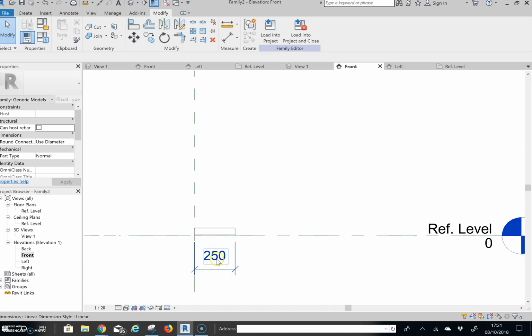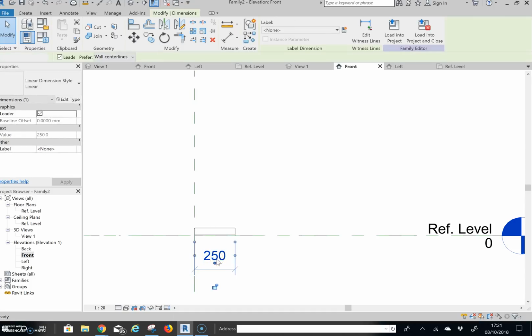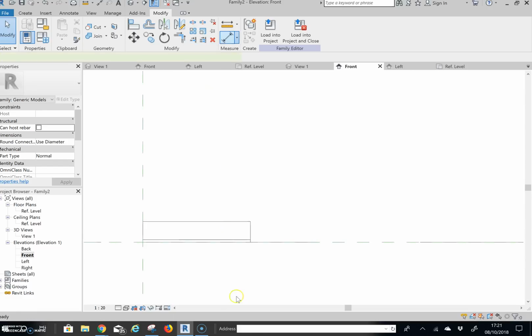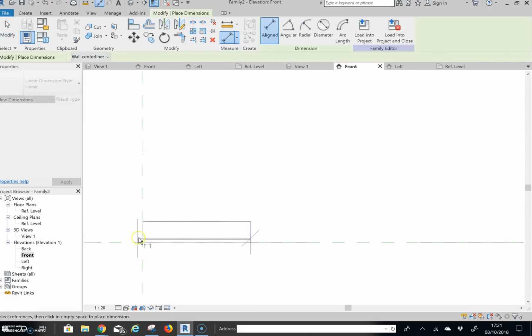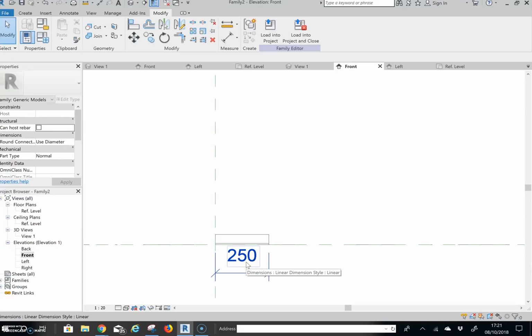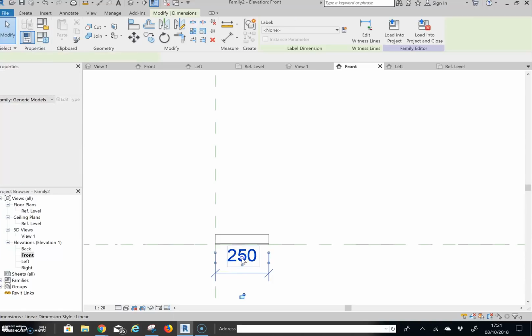That's the bottom flange, and here's the top of the T. Now what I've done here is added a dimension, so let me just delete that. If I added a dimension to say from here to here and place it here is 250, we know that 250 is the starting point of the extrusions. If I wanted to now make this into a parameter, double escape, I'm going to create something called a parameter, which means I can alter the length by giving this a file parameter.